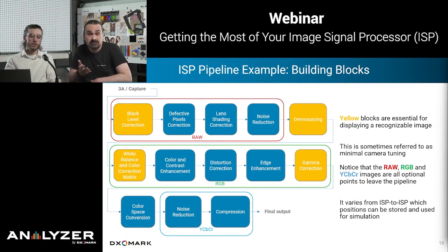It happens to be the red, green, and blue of whatever the spectrum of your Bayer filters are. Whereas the RGB space is some kind of standardized RGB space, so for instance, sRGB. And you have 3 samples, 3 channels per sample. So every pixel actually has a color. It has the 3 components, red, green, and blue.